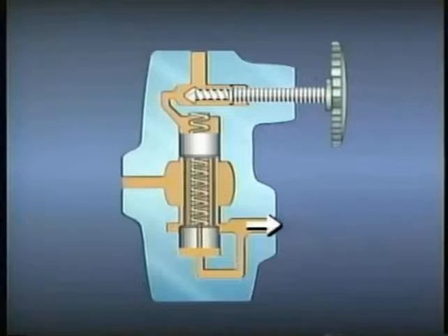Now, only enough fluid flows through the outlet to maintain the preset pressure. In this example, the outlet is never completely closed. When no flow is needed in the other part of the system, there is a small but continuous flow through the spool, the pilot valve, and to the drain. Well, that's basically the way this type of pressure control valve is used to reduce system pressure.